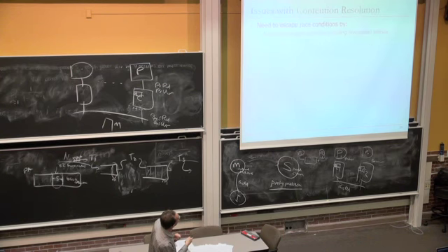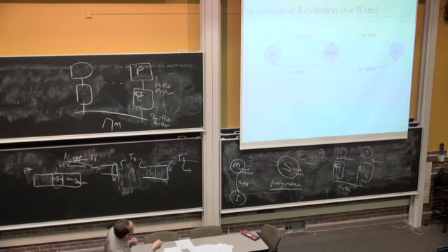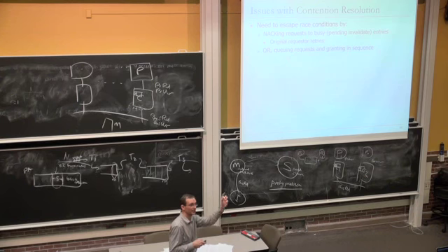One solution is actually not NACing the requests, but queue the requests, right? The directory can have a queue of requests. Basically, whenever it receives these two read exclusive requests, initially, let's go back to the beginning. When both processors send the read exclusive request, instead of granting, well, it needs to grant one, but instead of NACing the request and saying retry processor 1, it can queue all of those requests and service them in that order, right? That way, maybe you can eliminate some fairness issues as well, because now the directory sees all of the requests to that particular cache block, right?